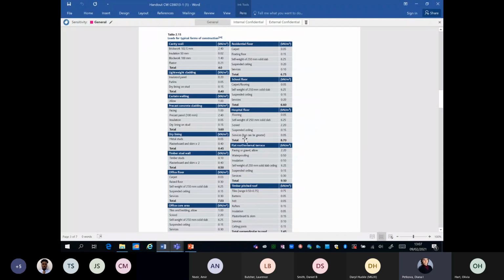So here, technically, what we have is a system that you can use. So some sort of flooring system. We have then the weight of the slab. We have screed on top of the slab, so probably something like 50 millimeters. Suspended ceiling, some services. So you're looking at permanent load as area load in the region of about 8-9 kilonewtons per square meter. Here, by the way, the assumption is that the slab is 250. So it will depend, of course, on your choice of depth of the slab. If you're going with 150, obviously this area load 6.25 will be an overestimation of your Gk.